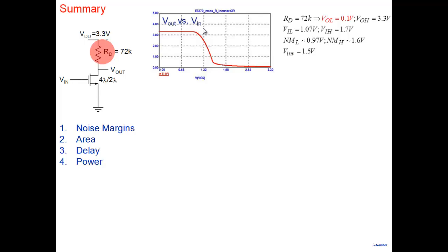How do we define proper? Proper VTC or a reasonable VTC. Right? So reasonable and all that, there were two things that we talked about in that sense. One was that when I look at a VTC, I calculate its inverter threshold voltage. It's a simple parameter called inverter threshold voltage. So you draw a line V out equal to V in, find out where it intersects, and you look at its inverter threshold voltage. And we said inverter threshold voltage, we should try and put it in the center.